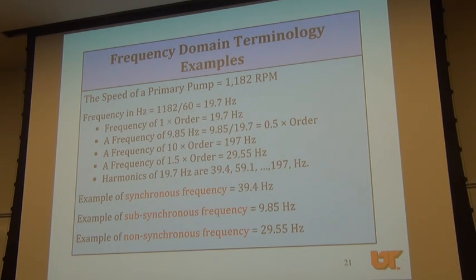It's kind of interesting. This number here says pump frequency is 1182 RPM. If the pump is driven by an induction motor, induction motors have what is called a no load speed. If I run the motor with zero load, of course there's always load, then it has a standard speed called the no load speed.